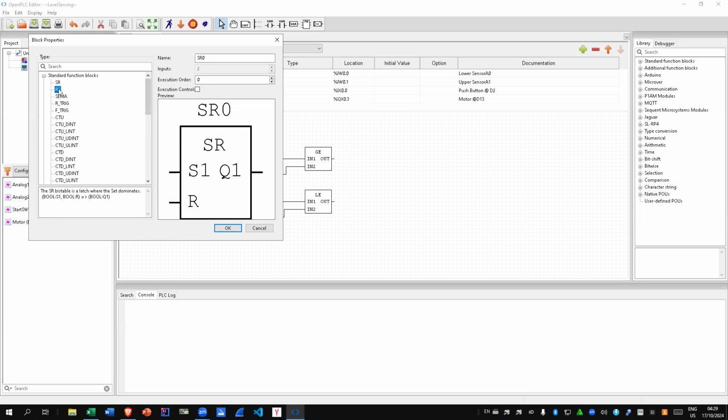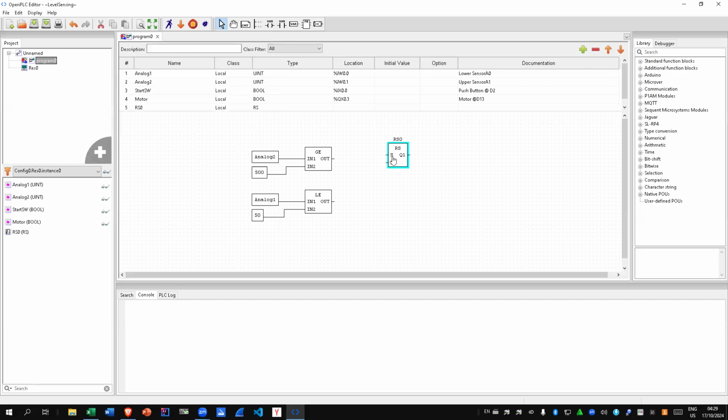Okay. For this one, we'll do the opposite. We'll do the reset dominated one. So, okay. So we get this item here. The reset action to stop the motor from operating is initialized by the value going equal to or above 500. Okay. So we can put that one there. Okay. For the other side, we just sequence it towards the less than or equal to.